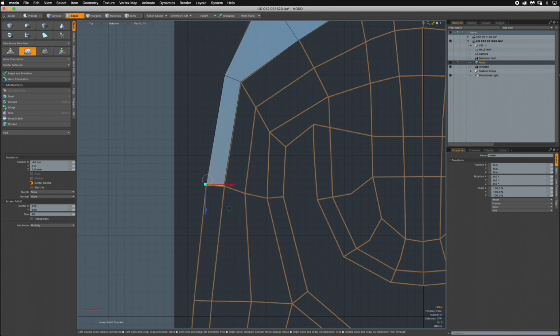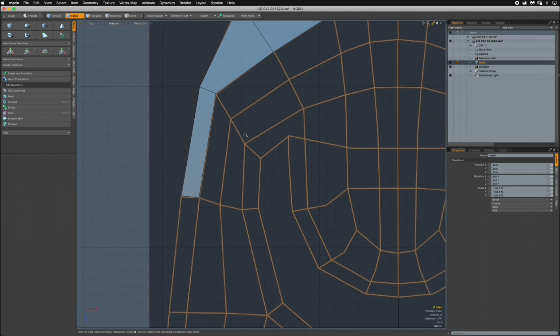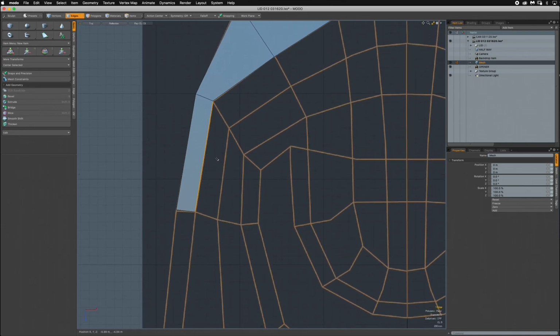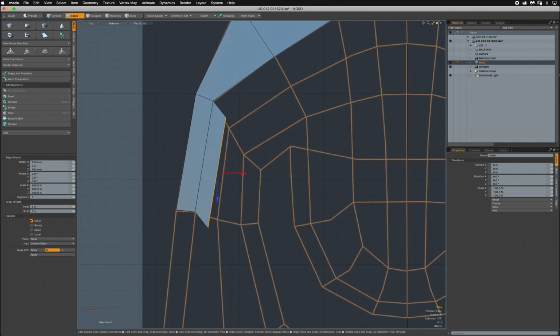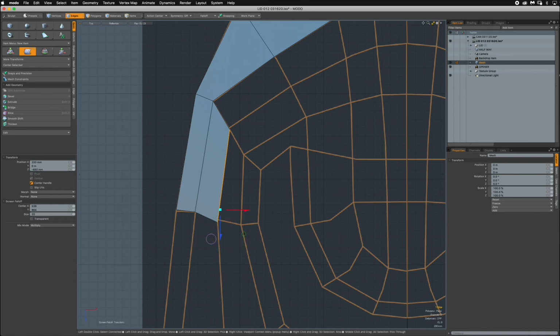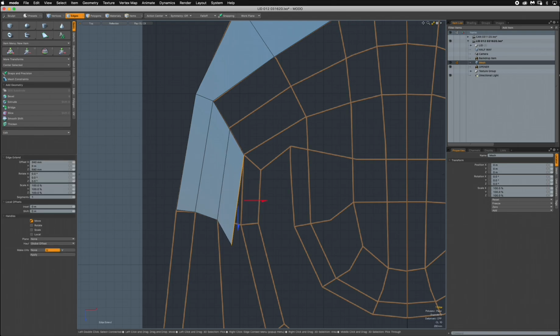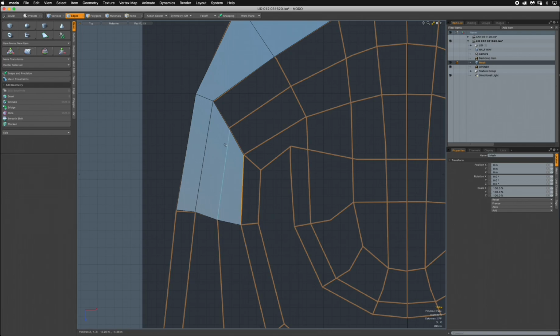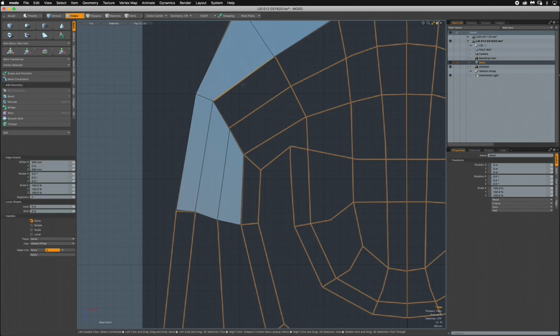Another tool that we'll be using a lot here is, if we select an edge and press Z to clone, then Control T to adjust. Space, Z to clone again, Control T, and then you deselect. Now you select an edge and Z, clone the edge again, space.